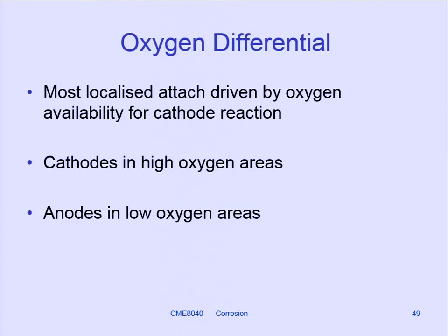So this tube actually perforated, and why it perforated was because debris and rubbish, as the tank was being used, slowly built up on the bottom of the tank. Sludge, waste, dust, muck. Eventually you ended up with a crevice situation along the bottom here.